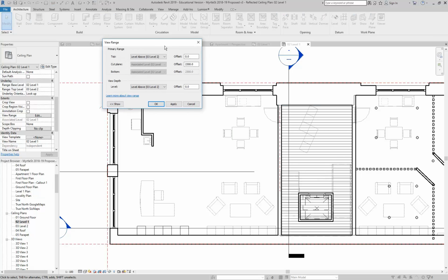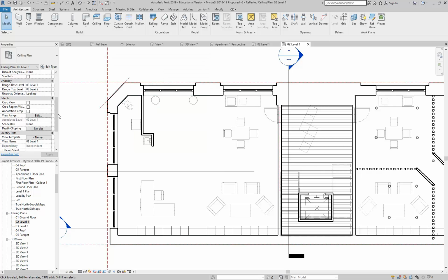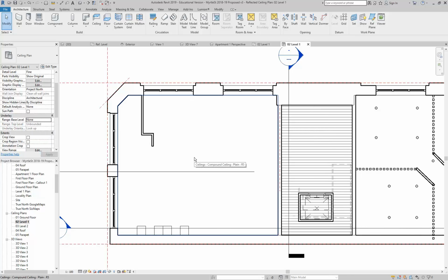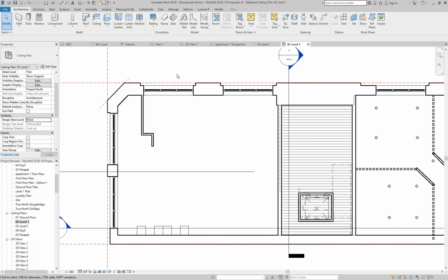And so notice how the door there, it's showing greyed out. I'm just going to fix that because you might not get that. So I'm going to set this underlay option here for the first, range-based level, back to none. And that's why you'll see in a lot of the views you get those greyed out lines. Right, that comes from the underlay. So I'll set that to none, and then the plan shows normally without those extra grey lines.